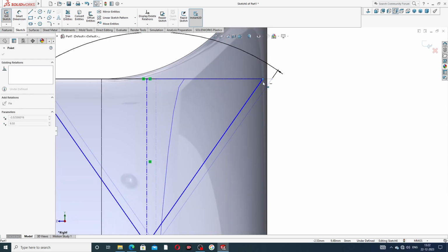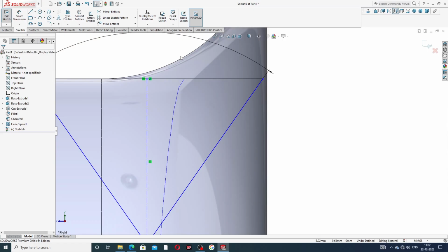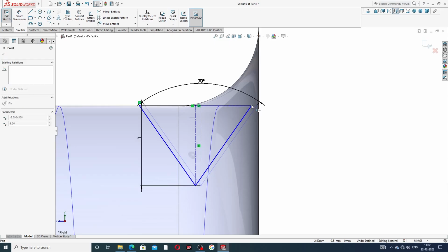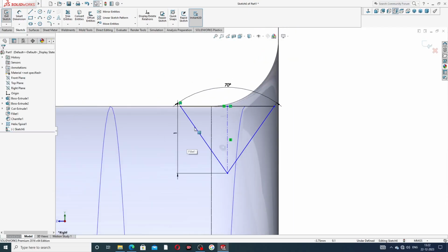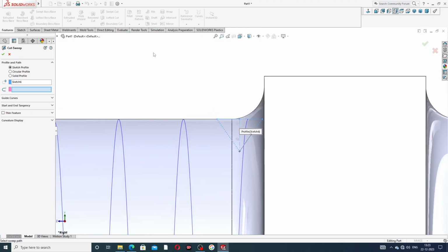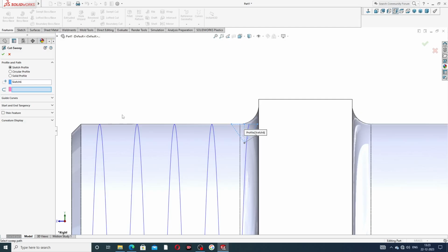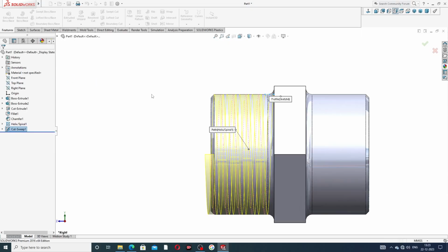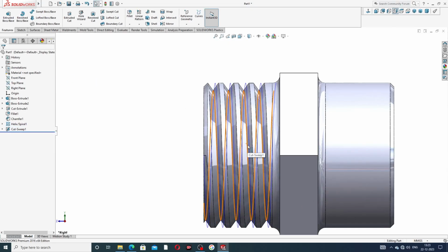This point is dragged here. Okay. Okay, this uses exit and going to sweep cut, and for sweep cut the profile is selected here, automatic here, and this selects a path. Okay, and path is okay, all is perfect and correct, and this cutout is very important.